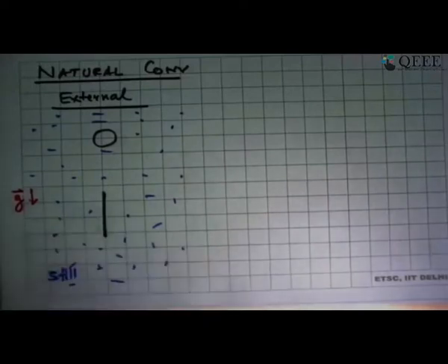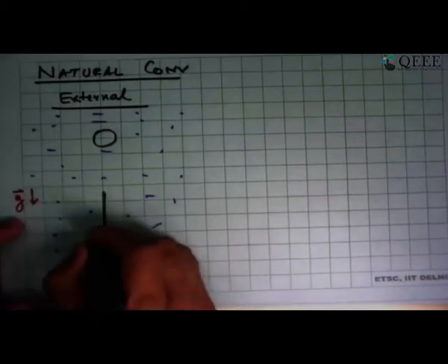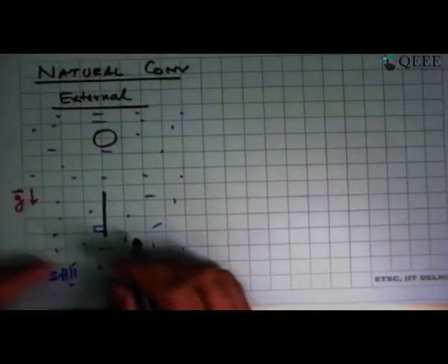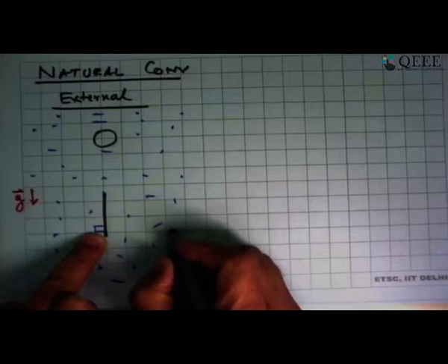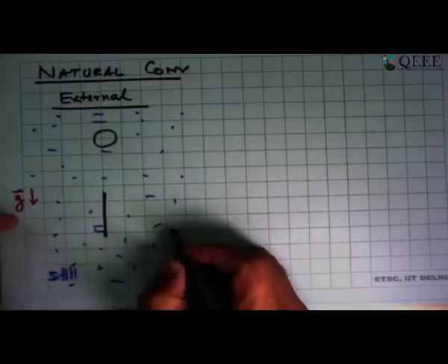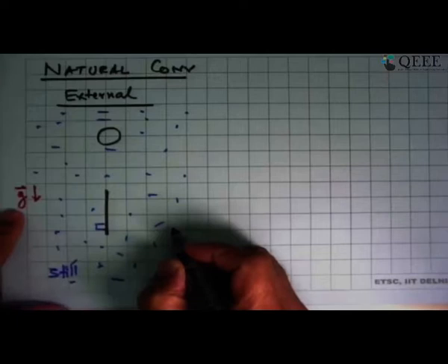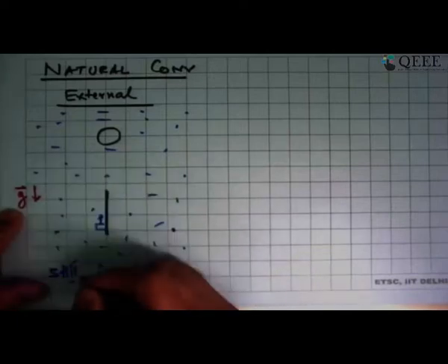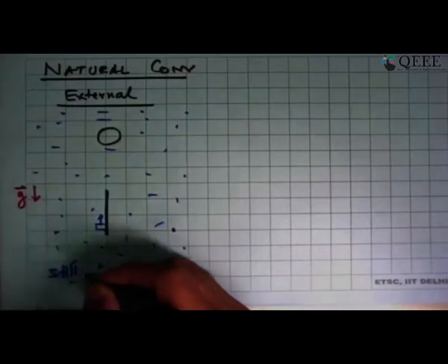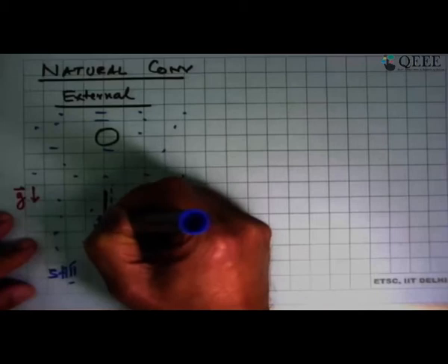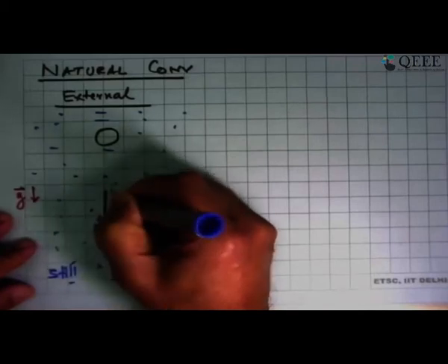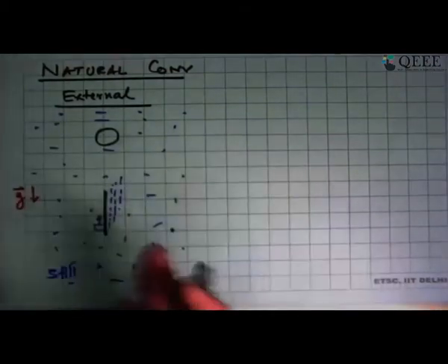What it means is that this fluid which was here next to this surface, say the surface was heated, this element had a temperature more than the temperature over here. And because there is a body force field being applied, this will experience a force and this will cause the fluid to go into motion. So this fluid element here will start moving up. It will induce an element further away from it to move because of viscous effects. This fluid will begin to move and pretty soon you have established a flow around this.